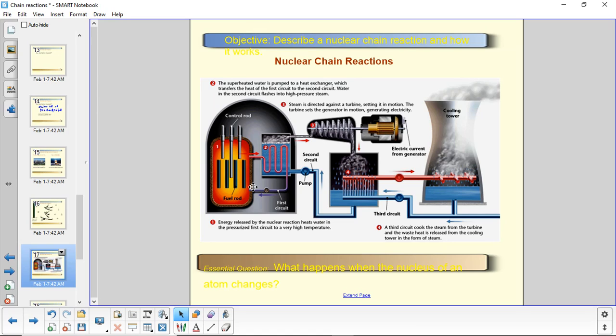So they use superheated steam, highly compressed water like a pressure cooker, to boil water, and that steam from that second tank of water, that's what goes out through a pipe that goes through the containment dome to the turbine and the generator. Okay, now they have radiation detectors inside this heat exchanger, and if one of the pipes from the nuclear reactor cracks, they close the valve and they stop any water and radioactive material from getting outside the dome. So that's the safety thing.